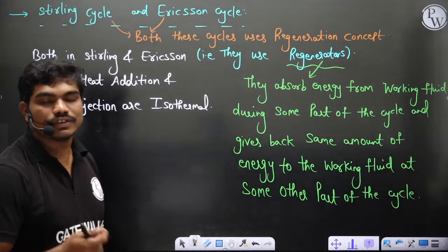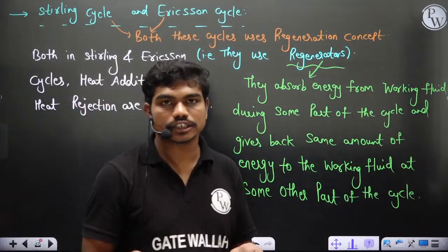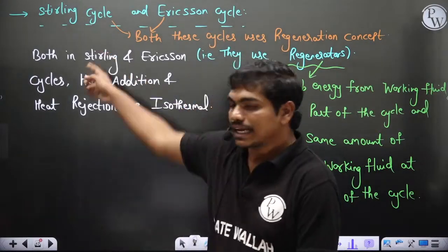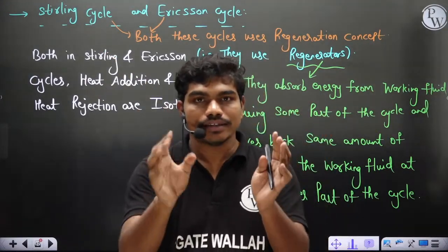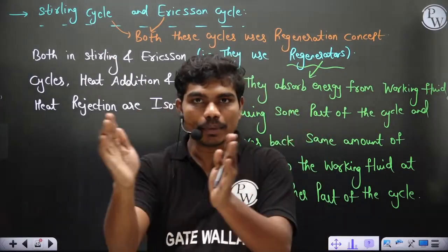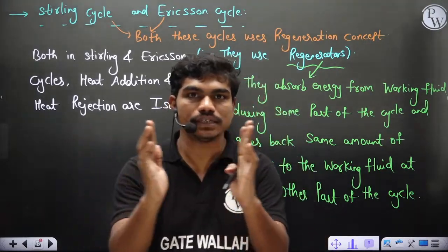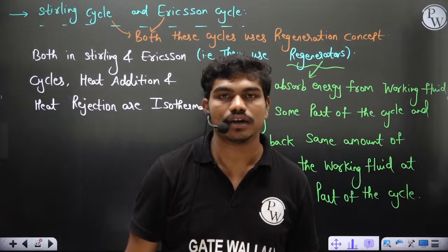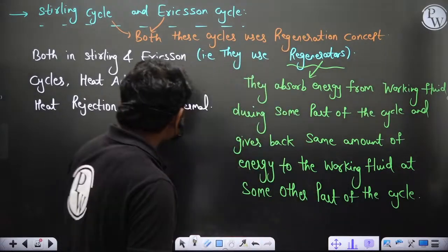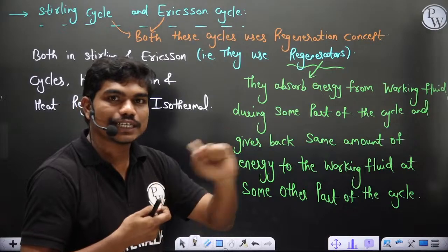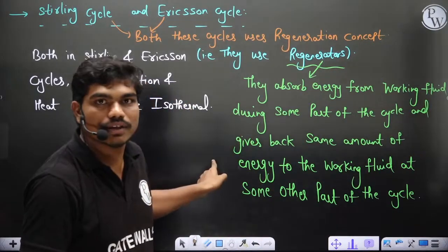Again, I'm not putting the physical construction, how piston and cylinder movement happen and all. Normally, in case of the Stirling cycle, you'll have two pistons, and there will be a regenerator in between. Depending upon the movement of the pistons, these two pistons move equally during the heat rejection and also heat transfer. And this compression and expansion, the changes in the states of the gas to bring it from TH to TL, will be at constant volume.